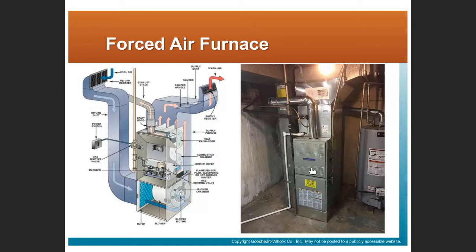So here's a diagram and a picture. This diagram is missing some components here. In this particular picture, there's also air conditioning included with the furnace. That would be this coil section that's sitting on top of the furnace, right? How did I know that was air conditioning here? Well, A, this is what I do for a living, but B, I see this pair of copper lines connected here.